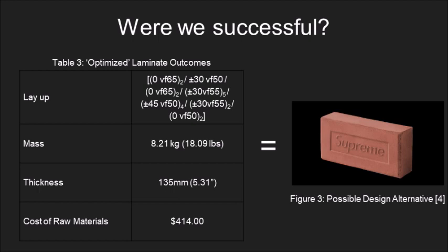Second, our laminate has a thickness of over 5 inches, and this is after being optimized. While it will technically withstand the necessary loads, it is closer to a brick than an effective composite. A laminate this thick would not only run into complications during the manufacturing process, but would also develop stresses and strains in the z-axis, making several of our earlier assumptions very wrong. All in all, we would not consider this an effective composite material solution to the problem statement.